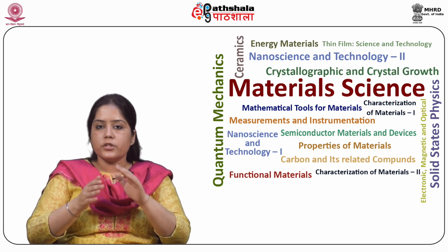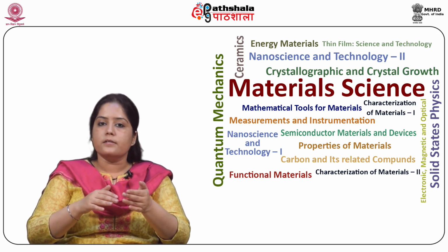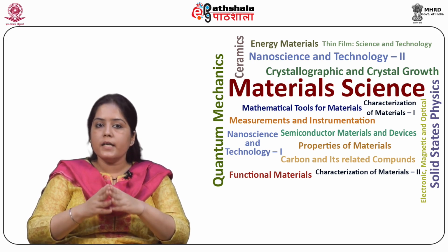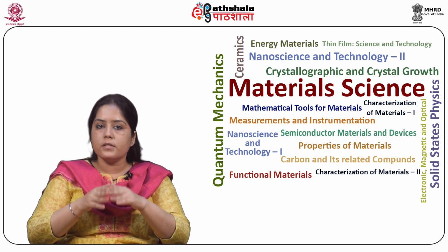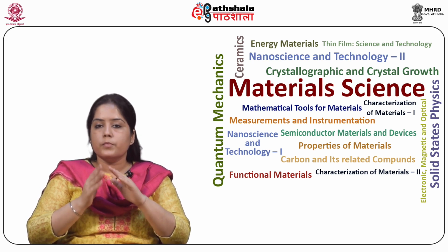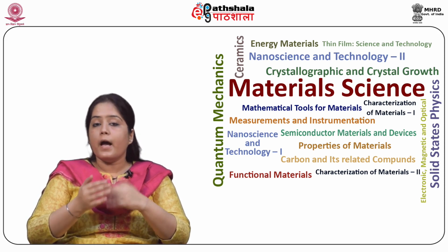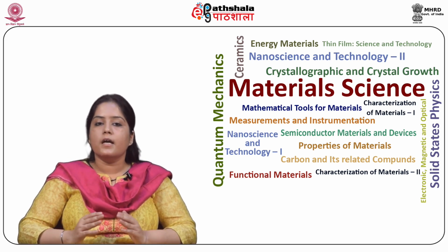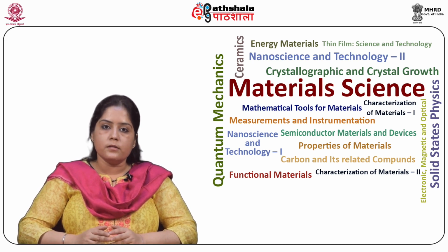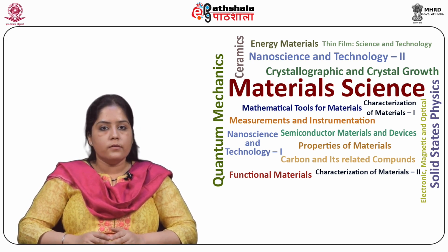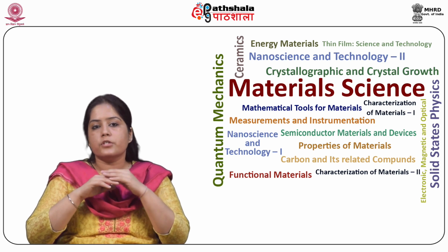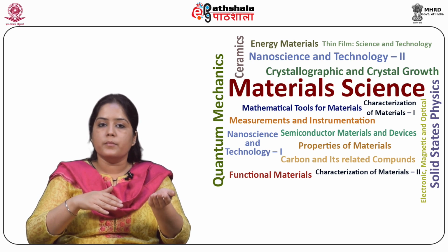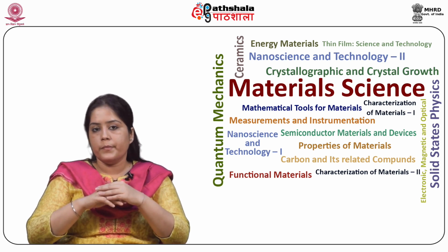Although the transfer of the vanadium ions through the membrane was found to be highly dependent on the concentration difference between the positive and the negative electrolytes, the cation and the anion exchange membranes tend to have net volumetric transfer through the positive and the negative compartments respectively.